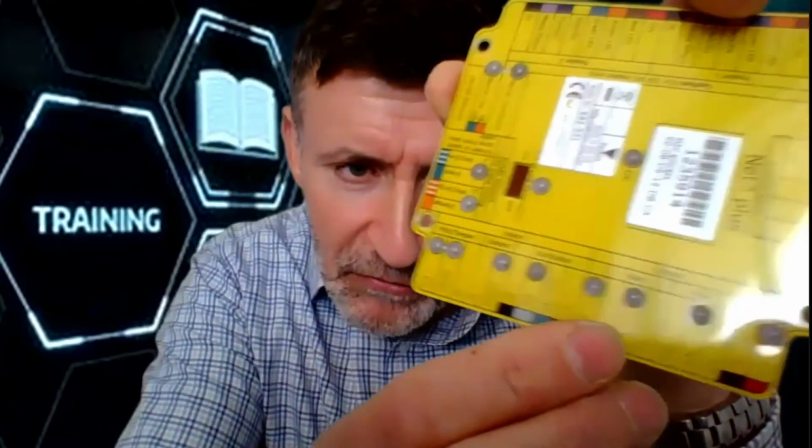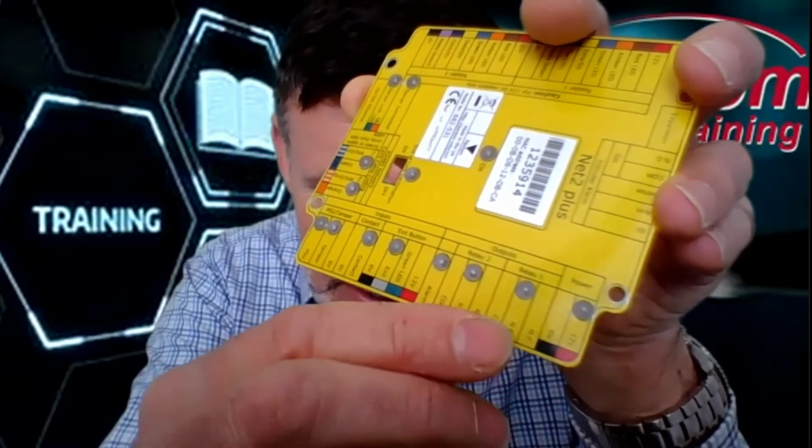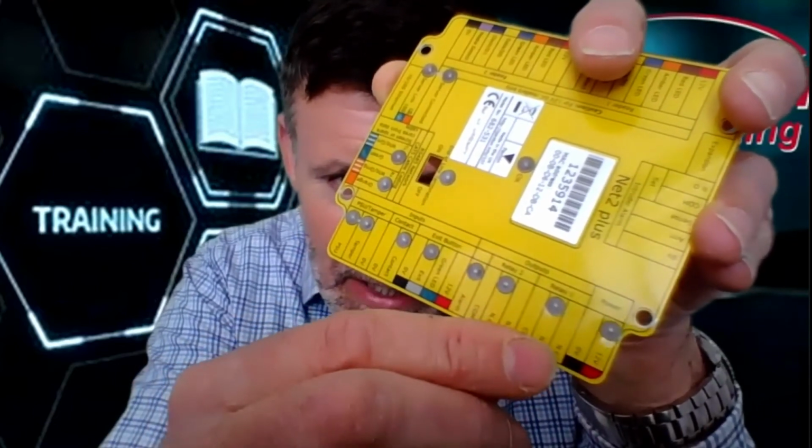This is similar to a light switch. The only difference with a light switch is that it latches in position. So we either switch the light on and it stays on, or we switch it off and it stays off. Where we find relays is generally on access control systems, where you can see, looking at this just here, there are two relay outputs. Now, with these relay outputs, this is what is going to either apply or remove power to your lock or your gate or your turnstile.